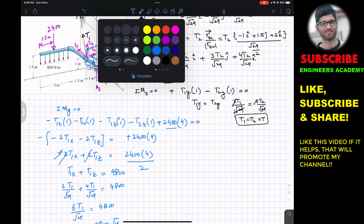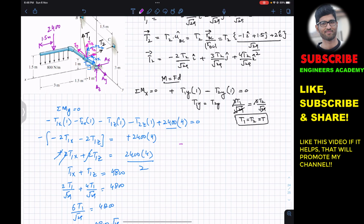Now if I apply the summation of forces along the x-axis, that will be equal to 0. As we can see, we have t1x plus t2x, and t2x is also equal to t1x since t1 and t2 are equal.